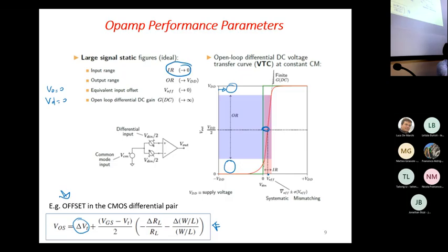around 0, okay? So the op-amp should be biased in a condition in which there is a virtual short circuit between the positive terminal and the negative one. But this is not the case, again, because the gain is not equal to infinity, but it is finite.